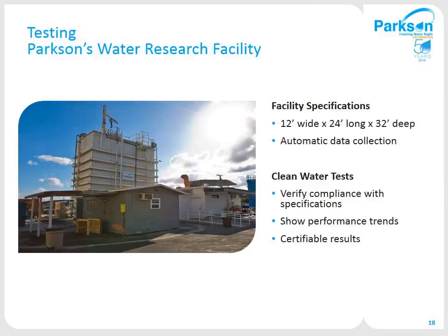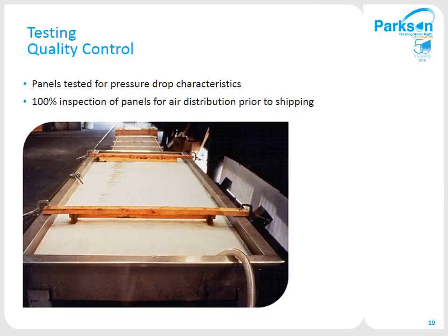For performance testing, we have the capabilities to test our systems at full-scale operating depth for development and performance compliance. Our facility includes a 32-foot deep tank, air supply blowers, automatic data recording, and limited lab capabilities. For quality assurance and production, we test every panel shipped to our customers for air distribution and pressure characteristics.